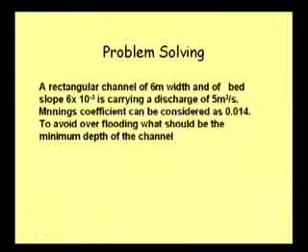First problem, let us take it like that. A rectangular channel of 6 meter bed width, you can concentrate on this slide, and of bed slope 6 into 10 to the power minus 3, is carrying a discharge of 5 meter cube per second. Manning's coefficient can be considered as